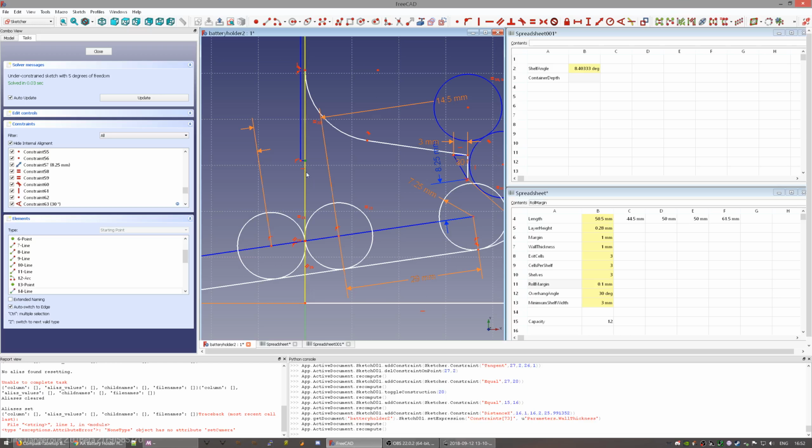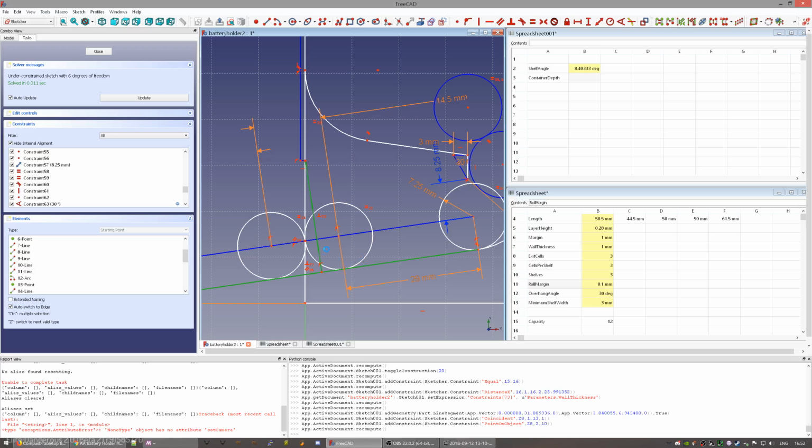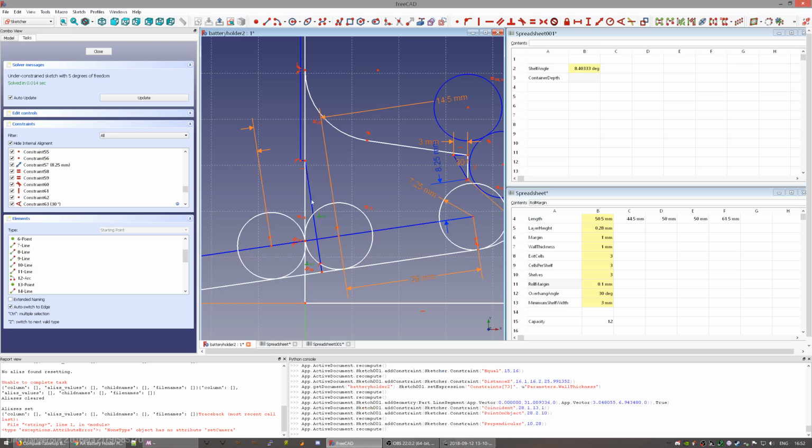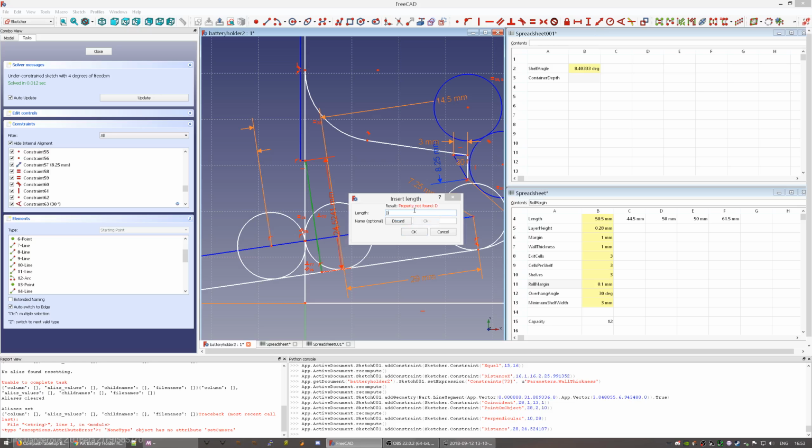We also want this point to allow that is passed. So we shall place another construction line. This construction line goes from here to here. We make this normal, that's n, such that it describes this opening. And now I can constrain the length of this line to, again, diameter plus margin.